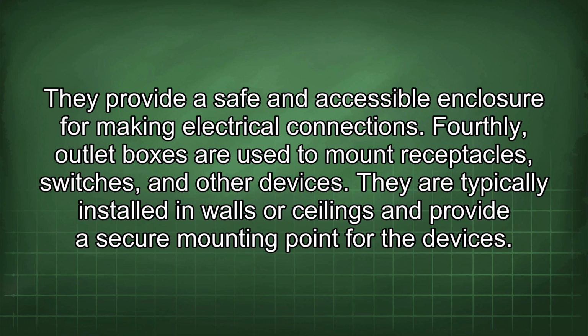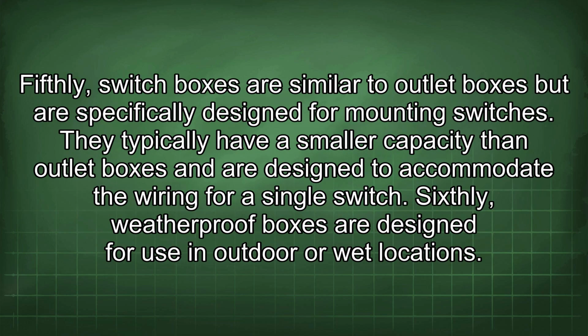Fourthly, outlet boxes are used to mount receptacles, switches, and other devices. They are typically installed in walls or ceilings and provide a secure mounting point for the devices. Fifthly, switch boxes are similar to outlet boxes but are specifically designed for mounting switches. They typically have a smaller capacity than outlet boxes and are designed to accommodate the wiring for a single switch.